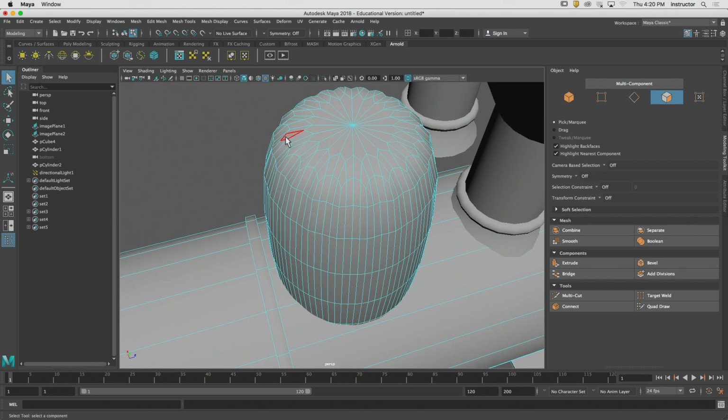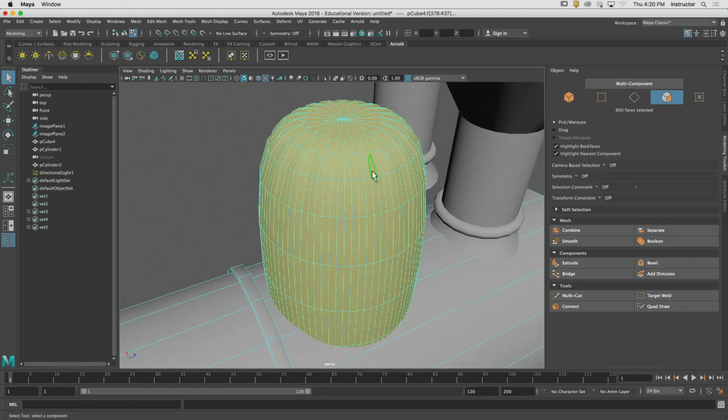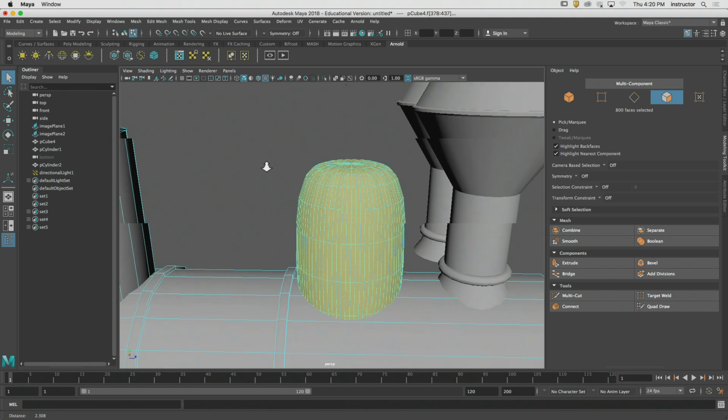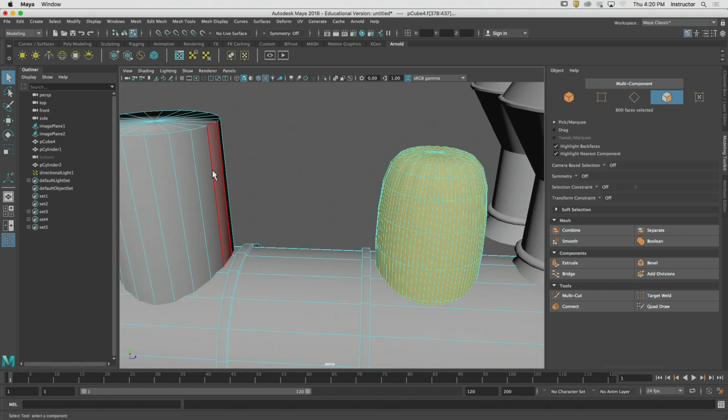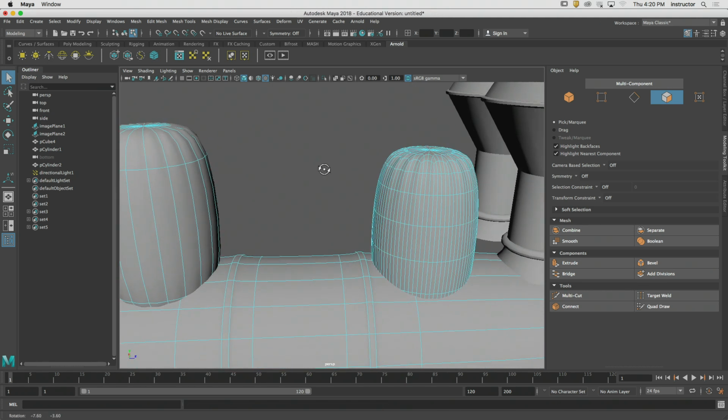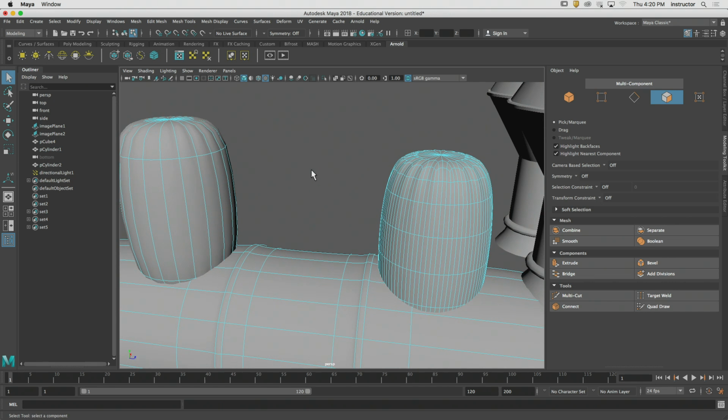I try the smooth tool in all earnest. Okay, next week we're going to talk about the modern day alternative to the smooth tool. The smooth tool is kind of a system of 20 years ago. We have a new surface type in 3D modeling. Actually, it's not new, but the preferred one is called subdivision surface modeling, and we're going to be talking about that very directly next week. Sub-Ds are a way for us to interactively smooth our shapes, kind of get something like that, but at the same time, go back to an unsmooth state.